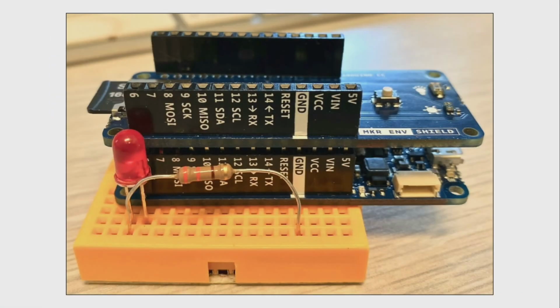This is the shield stacked on top of the Arduino. Literally plugs into the same pins, and now it's connected up. You could still access the pins it's not using. So I think it takes over the LED pin, for example, so you have to use something else for the default LED. But if you want to use one of the general purpose I/O pins, you could do that, as long as you're not using one of the ones that it's using. And in this example, we have it wired up with an LED, and in the wrong location, Don would say: pin 6, which he moves to pin 5, I think, in his experience.